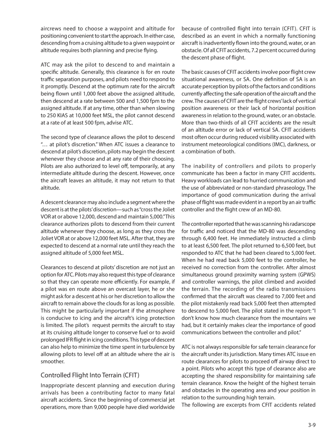ATC is not always responsible for safe terrain clearance for the aircraft under its jurisdiction. Many times ATC issues en route clearances for pilots to proceed off airway direct to a point. Pilots who accept this type of clearance also are accepting the shared responsibility for maintaining safe terrain clearance. Know the height of the highest terrain and obstacles in the operating area and your position in relation to the surrounding high terrain.